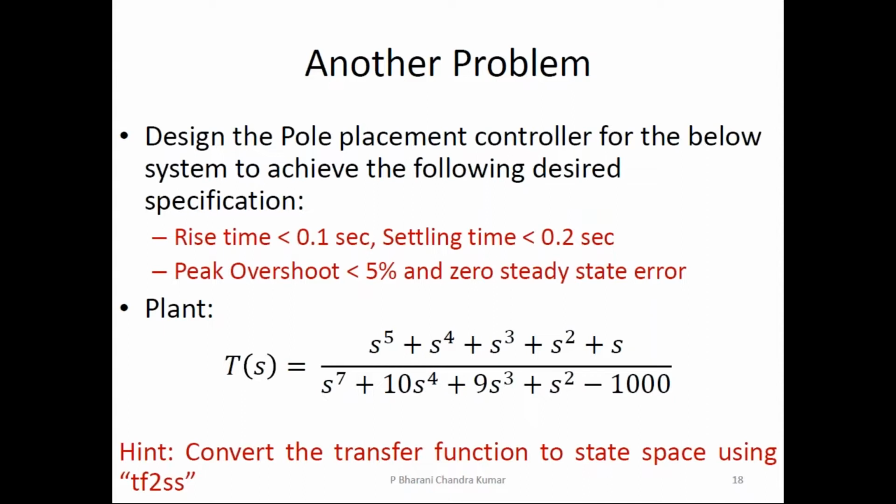Sir, this is Appara from Venkateshwara College. Coming to the DC motor, we will write the transfer function, write the program accordingly, and get some poles. Without the controller we get some rise time, and with the controller a different rise or settling time. Then what are the physical modifications? How do we know what we have to do for the motor, on the supply side, motor side or winding side? Suppose the speed reached 1500 RPM in one minute, and now we have designed it for half a minute, based on our poles.